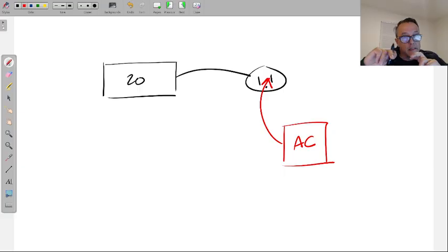Now, when this air conditioner starts, there is an effect that happens to the amperage, because a load sometimes requires a lot of energy when it first starts to get things going. An air conditioner, because it has to compress that gas, is one of them. Refrigerators are another one. One of the big ones are motors, and I'll get to the difference here in a second.